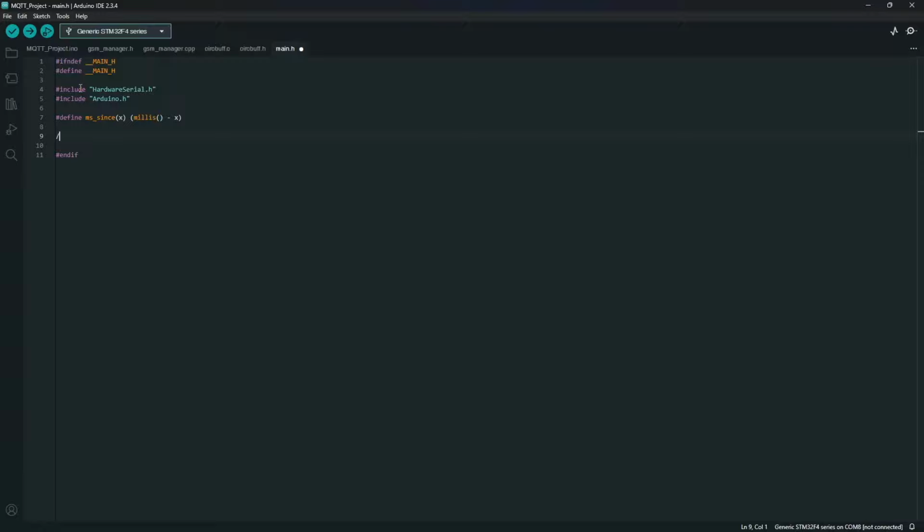From there, what I'm going to do is the GPIO setup, and in this section, define the pins that we will be using for our GPIO. That's the interface I just explained, starting with our GSM power key. On my board, I'm going to route that to pin PB2. And then I'm going to define a pin for my GSM status. That's going to be GSM stat, and I'm going to put that on PB1.